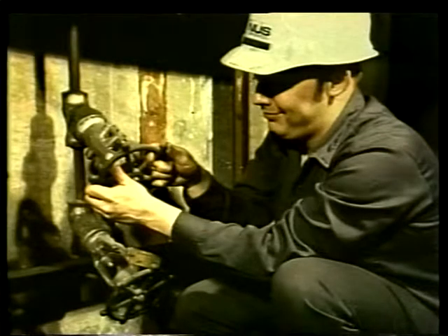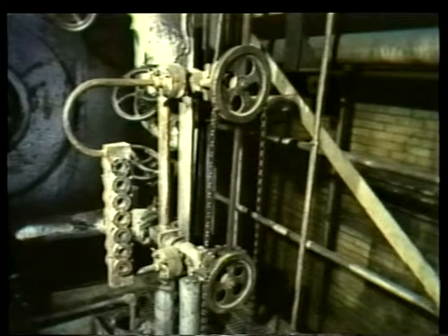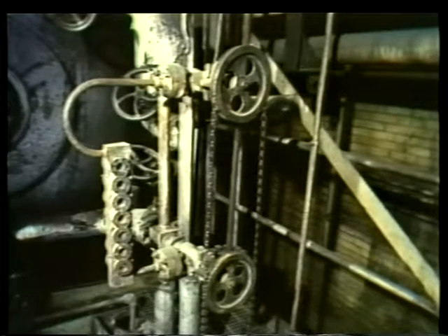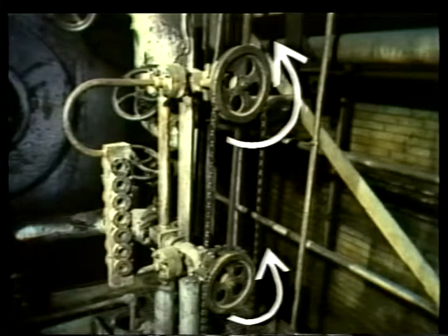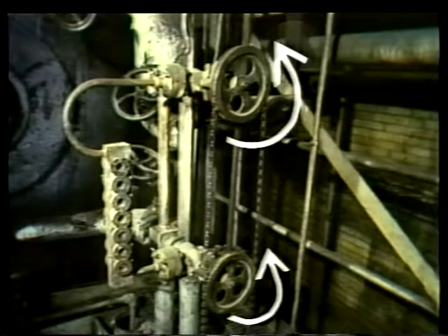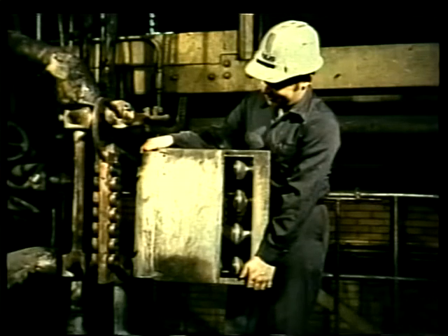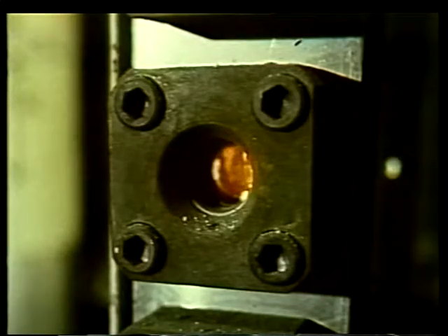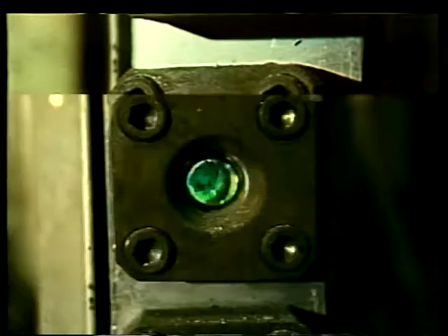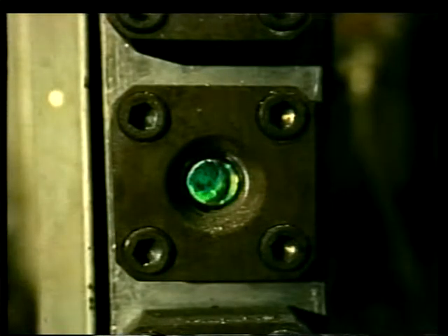The manufacturer recommends that the cap screws in this multiple port gauge glass be retightened with a torque wrench whether there are leaks in the gauge or not. After retightening, reheat the gauge for about 5 minutes. Close the drain valve and let the gauge fill up. Once the gauge is full, it can be returned to service by slowly opening the upper and lower valves. Finally, reinstall the illuminator. Make sure that the upper portion of the gauge shows red and the lower green. If it does, the job is finished.